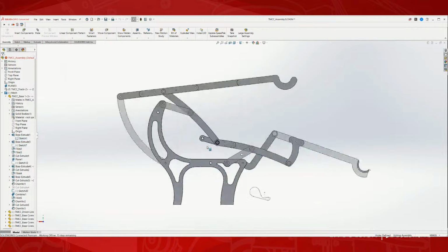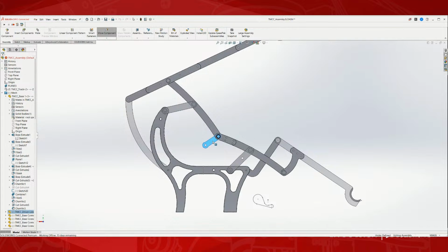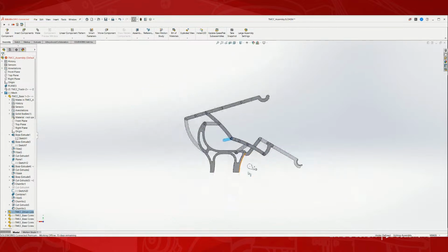But for the lifter, I basically just used those dimensions, and I used a tool outside of SolidWorks called Motion Gen, which is kind of like sketching in a notebook, but for mechanical design. It was really helpful for me to get an idea of how adjusting each one of these dimensions adjusted the trajectory of each one of these linkages.